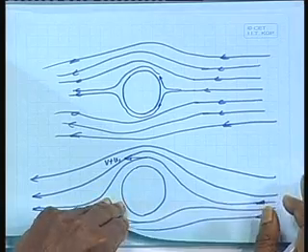So, this is the principle of vortex flow, that if there is a vortex superimposed on a free stream flow, it will impose a vertical force to the direction of free stream flow on the object. This is similar to what we call a lift force. That means, now if you have an aerofoil section, you can consider that when it is at an angle of attack, instead of doing the analysis that we did before, we could also represent it as if there is a free stream flow and a circulation around the aerofoil, which is causing a lift, as we have seen.